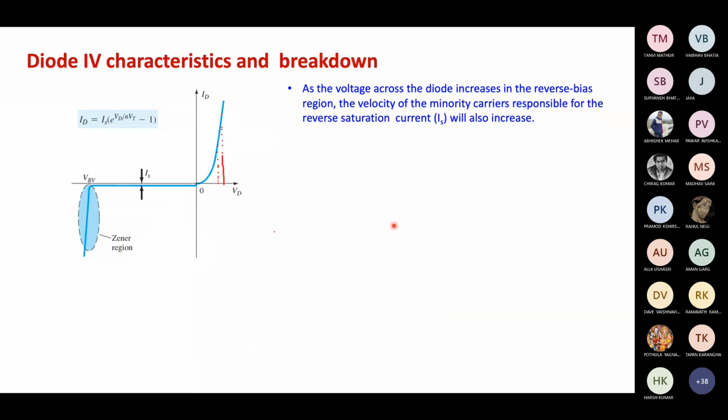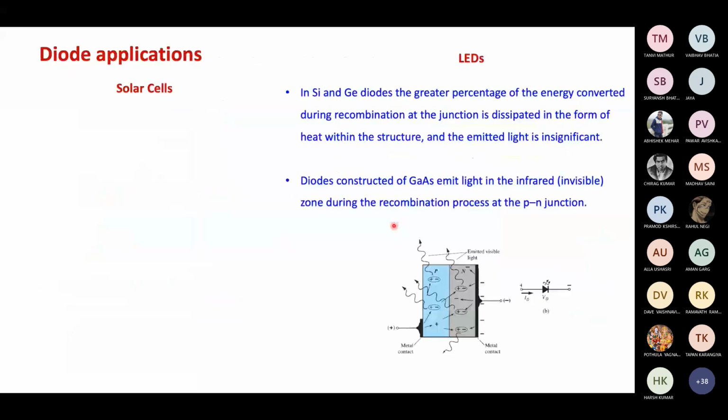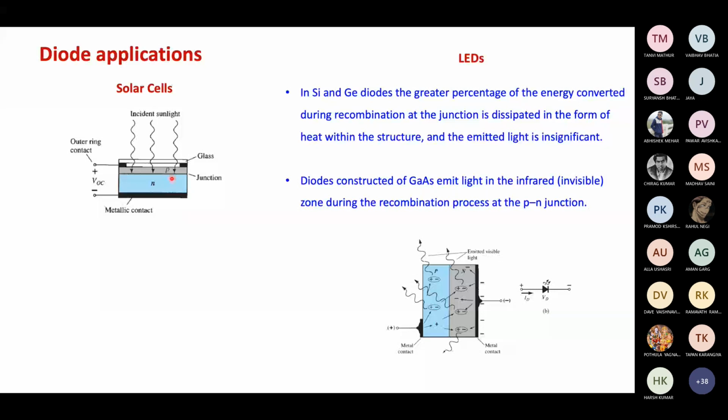That is the kind of diode we generally have in solar cells, in which the N side is heavily doped, so that almost the entire P side is in the depletion region, and any electron-hole pair generated in the P side or slightly into the N side is separated. The electrons and holes are taken away from each other.